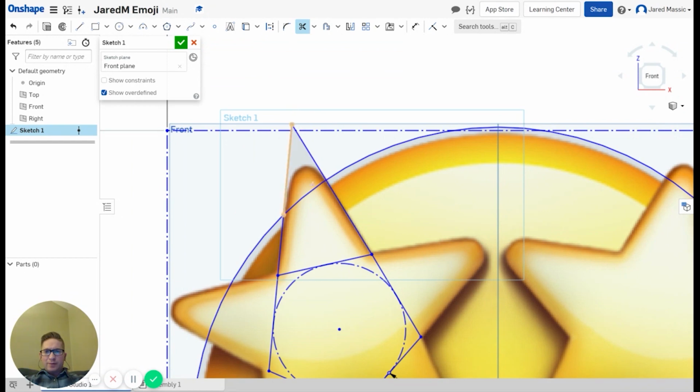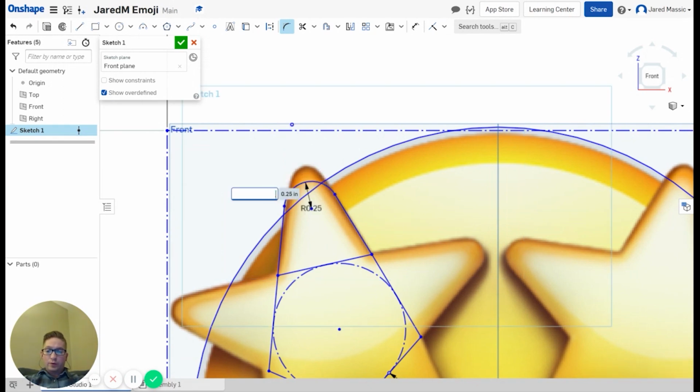And you're like, well, Masick, that star, what's going on there? I can go to this thing right here. It says sketch fillet. Now, a fillet is basically a round. I know a fillet weld. You're thinking what I'm thinking, but a fillet in drafting is rounding a corner. So I click on this corner. You can see with a radius of 0.25 or a 1/4 inch, it's taking it down here. There we go. I'm going to put 0.15.